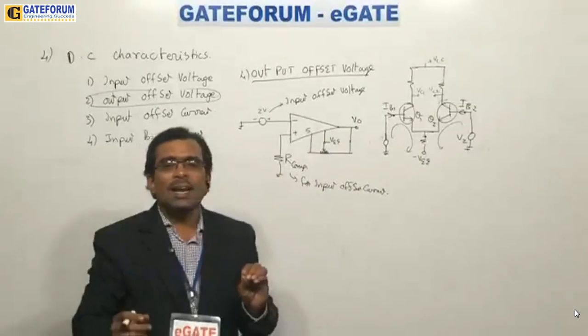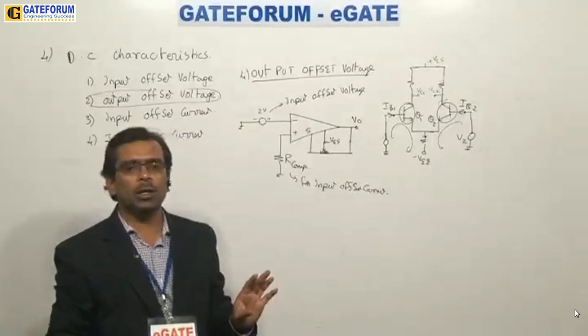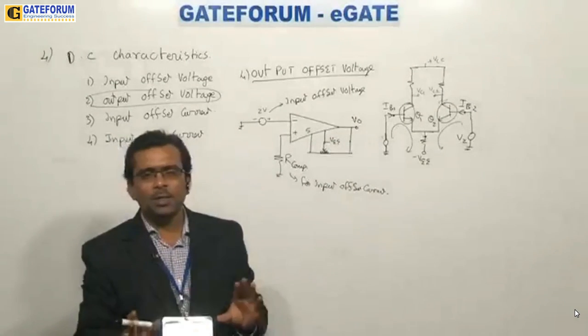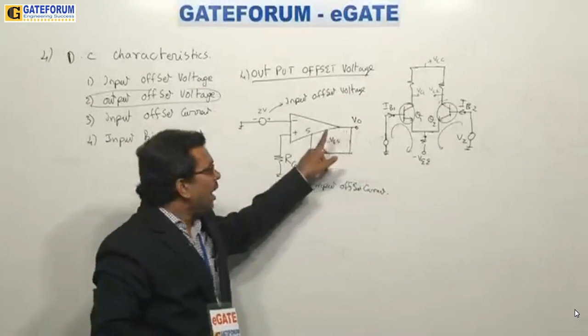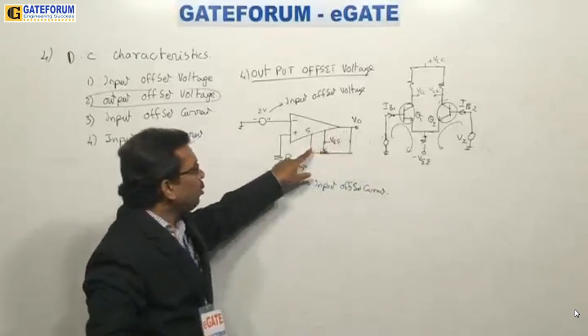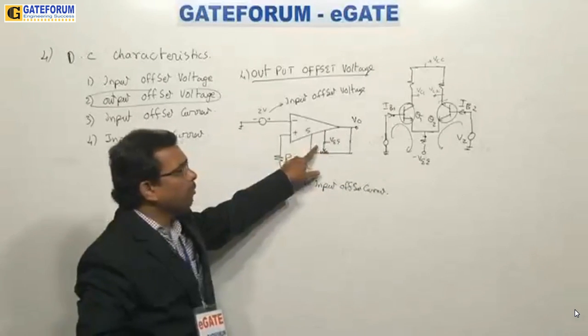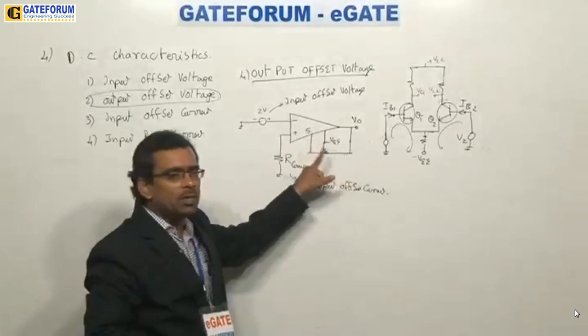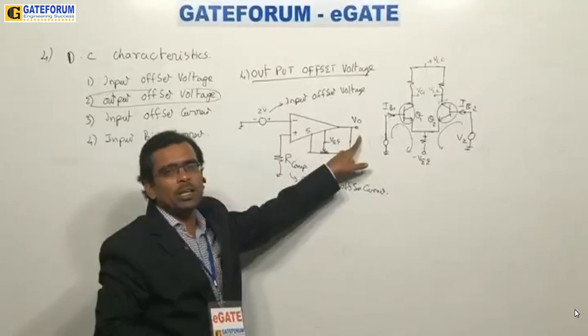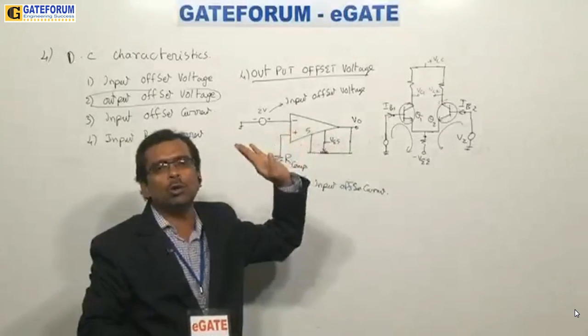Now what happens is, let there be 100 errors, we don't bother about it. If I get any error voltage here, I'll take the supply from this potentiometer connected to pin number 5 and readjust this here. Once I readjust it, whatever output voltage you get here will be nullified and made to 0.